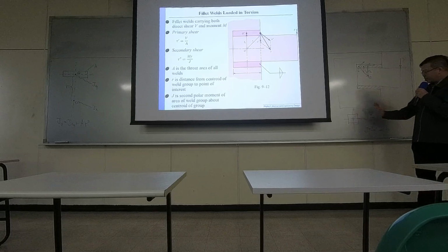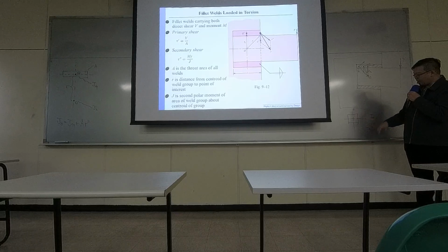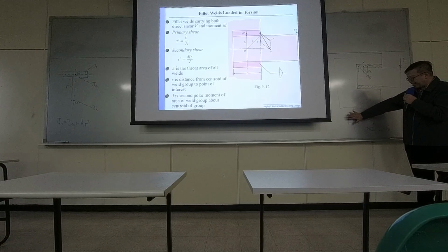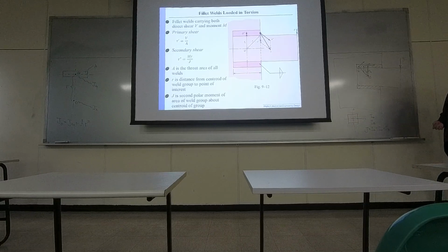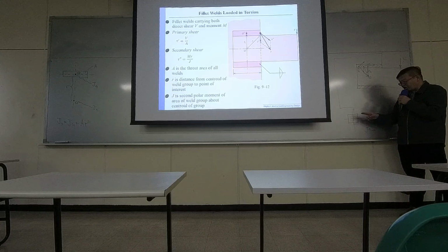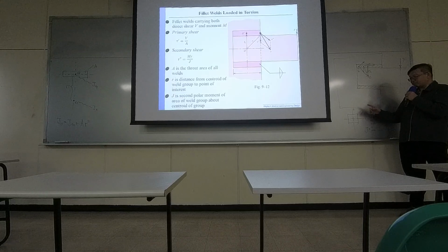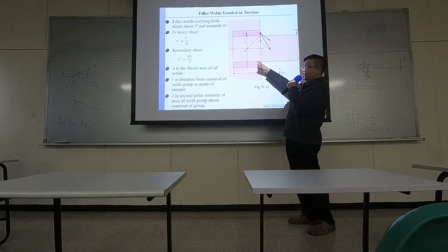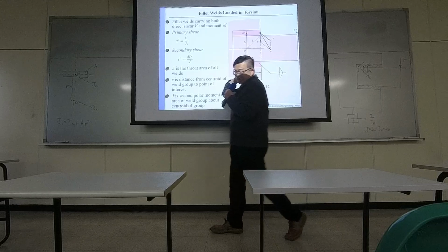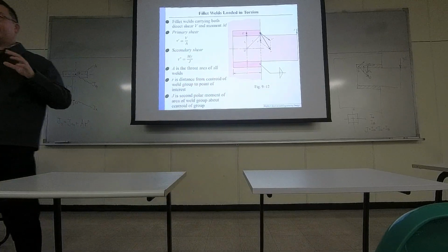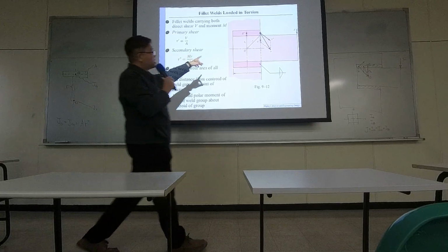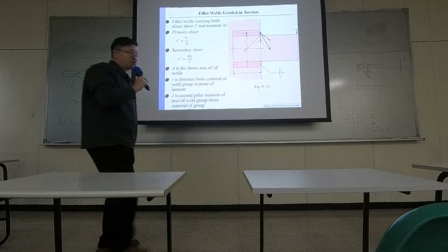So if you have a torsional shear that is rotating on this particular plane, then the area moment of inertia you are studying is the one rotating about the z-axis. So here we are doing that. If you have a larger J, the material can carry heavier loads that generate this kind of rotational shear.